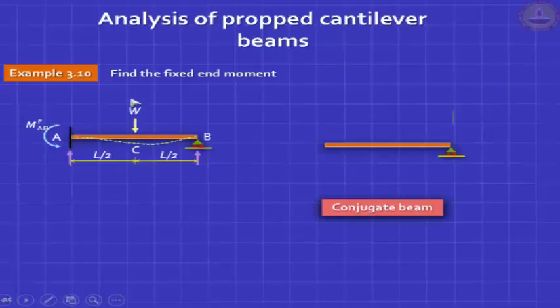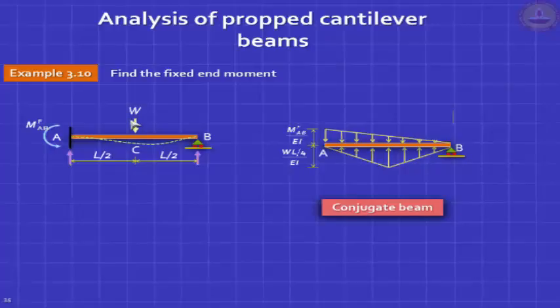First, the diagram caused in the simply supported beam, the sagging moment diagram, which we all know is going to be like this, WL by 4. Then the hogging moment diagram will now look like this, because you have only one fixed end moment here and 0 fixed end moment here. These two now must self-equilibrate. Got it? That information is enough for you to solve the problem.